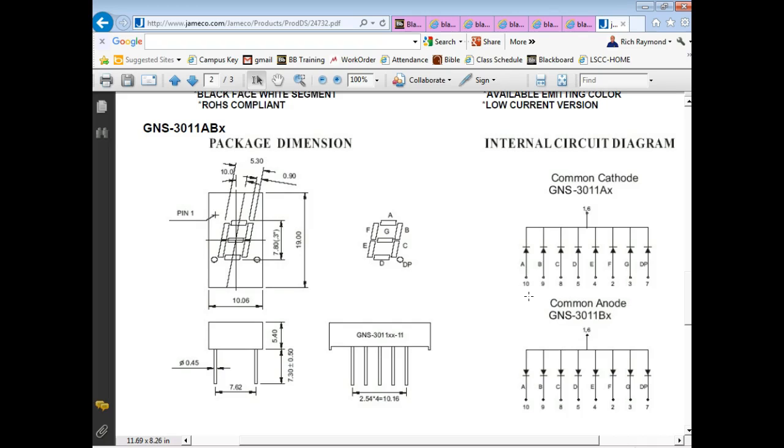That makes sense. Now, the problem we have is that standard TTL supplies are 5 volts, right? You understand? If I put 5 volts across the diode that starts conducting at 2 volts, as soon as I put it on there, it'd blow the LED. So what do we need? Start with R. Resistors. We need resistors.